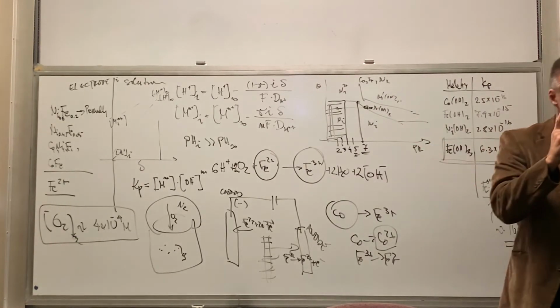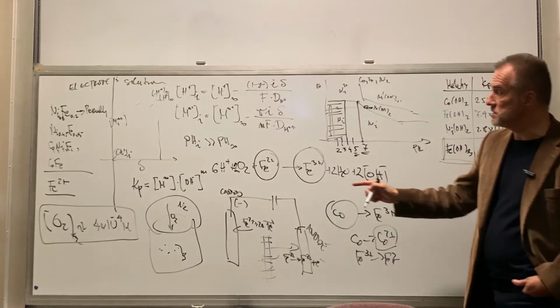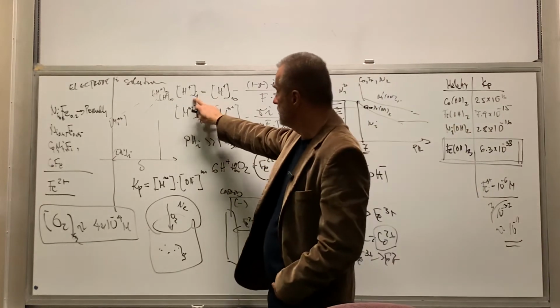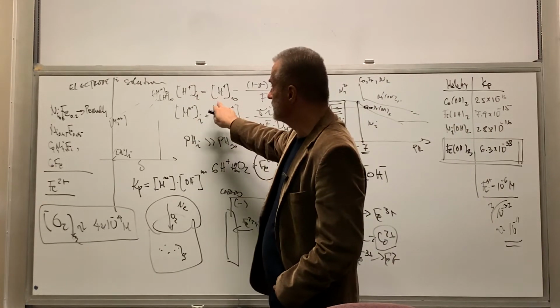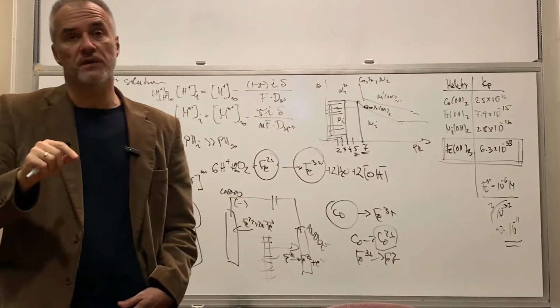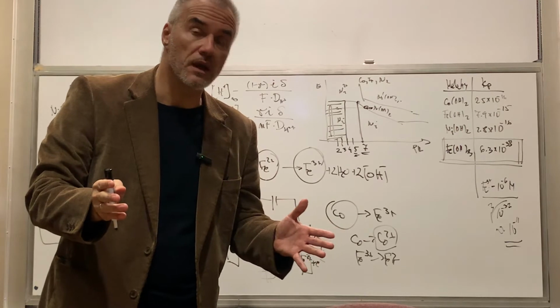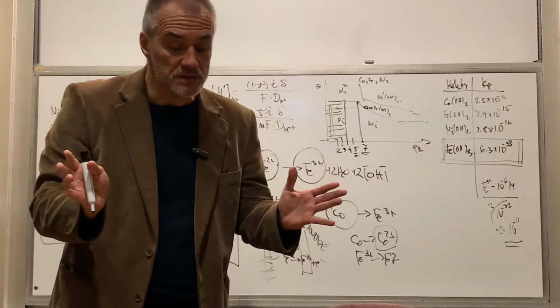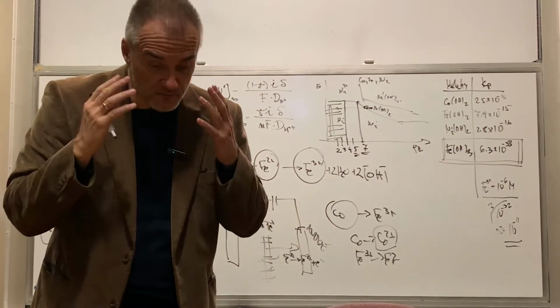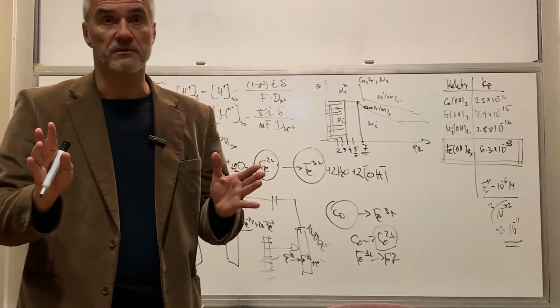precipitation, not only in the bulk, which is the end scenario, but because what we just discussed, that this and this is different than the bulk, your precipitation of iron 3 hydroxide will be affecting your process before you even see anything wrong with the solution. And when you see something is wrong, that means the solution looks like crap. You can see visually rust type of color. That's the end of the process.